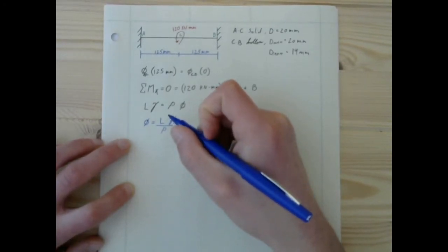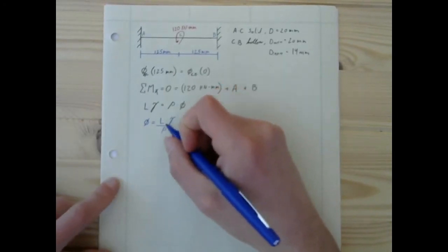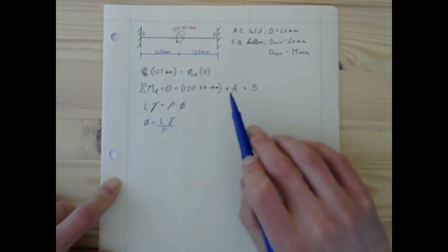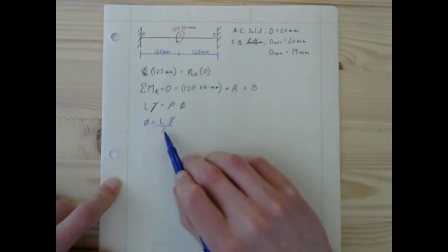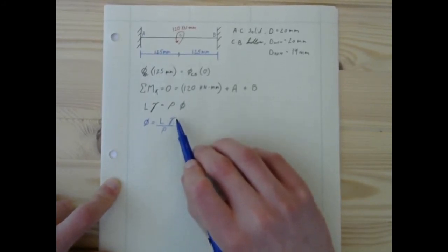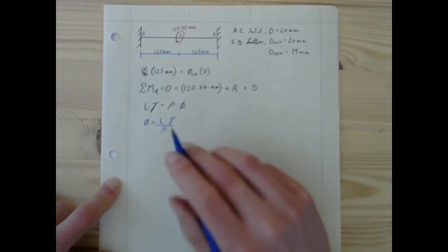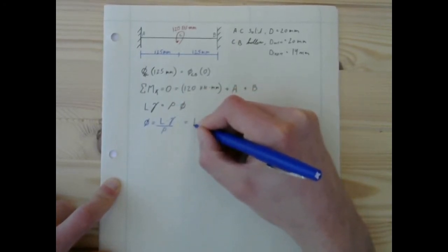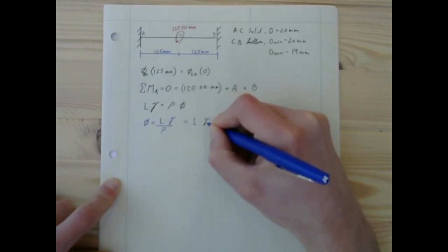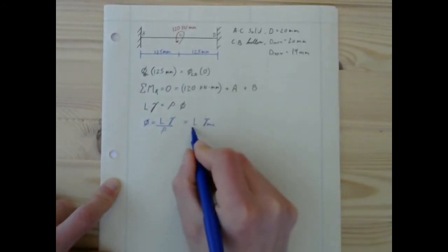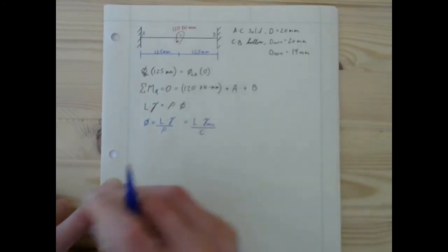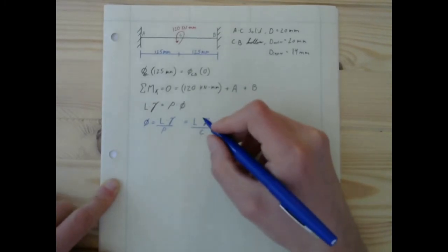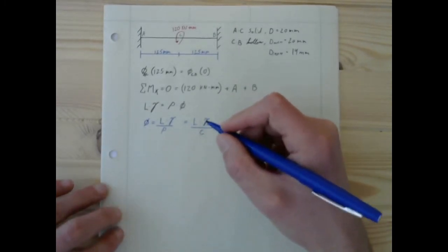And we don't have to think about this as a function of the location as we go out from the center, because the shear strain is going to be a function of our radius. So obviously this will also be L, the maximum shear strain for our outer radius. That's probably the easiest way to deal with this.